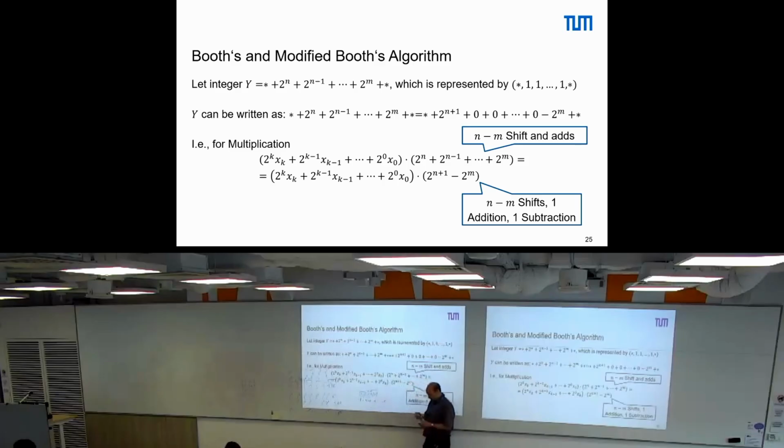Okay. Now I do the following. I take this, invert plus 1, because maybe that's easier feasible. If I invert this, I have 0, 1, 0, 0. So if I add 1, I have 0, 1, 0, 1, which is binary plus 5, sorry, right? So what did I do here? Effectively, by interpreting this in that way, this is automatically interpreted as 2's complement.